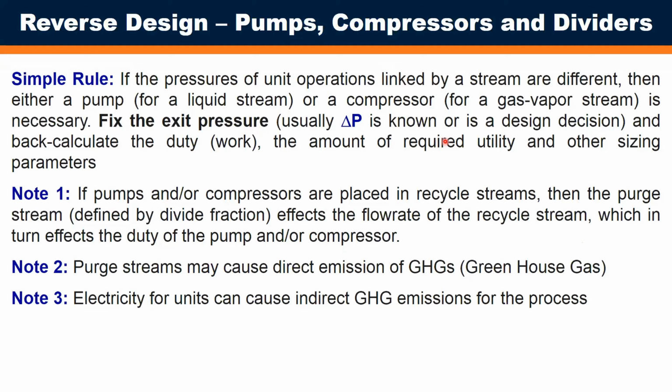A quick side note here to think about: depending on the conditions, you may actually be better off achieving a certain pressure and temperature change by taking a gaseous stream, condensing it, and pumping it to a higher pressure and then re-vaporizing it.